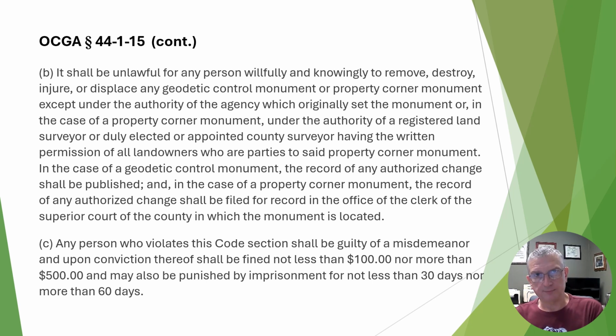Now let's go back a few slides and think about this. If you're driving a pin to perpetuate an old position, say you found a rotten locust stake or the rusted iron pipe that I talked about, you're not removing it, you're just perpetuating it. You're not even in the realm of OCGA 44-1-15. But if you're plucking that pin up, then that's when this law drops in.